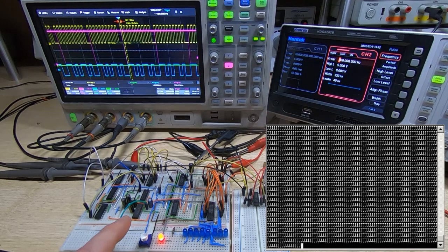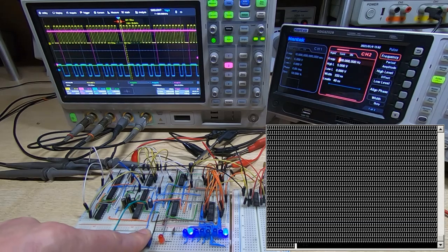So the Z80 would normally respond by reading the data, which effectively is what happens when I press this button. We should see the hex value for uppercase A appear on the LEDs, and the red LED should go out, which it does. So we're getting 4 and a 1, which is 41 hex, and that's the correct value for an A. Also, when I release the button, this will go back out.